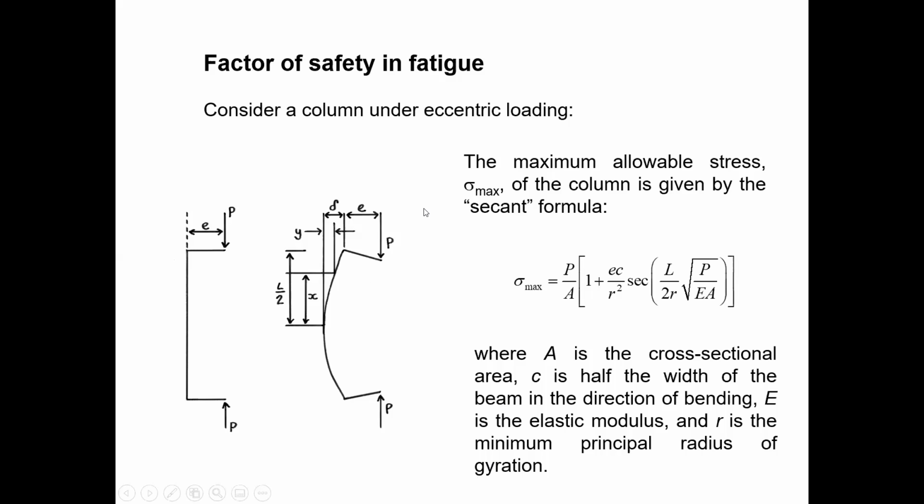If you get something like this, I will draw here. If you have this kind of cross-section, you can't calculate the area and you can't get any dimensions. But if you introduce a circle, assume this is a circle, and this cross-sectional area is equal to the other, then that radius is called the radius of gyration. These two areas should be equal. Then the circle radius is called the principal radius of gyration. So we will discuss it later. So hope you remember this equation now. I mean, get a rough idea about this equation.